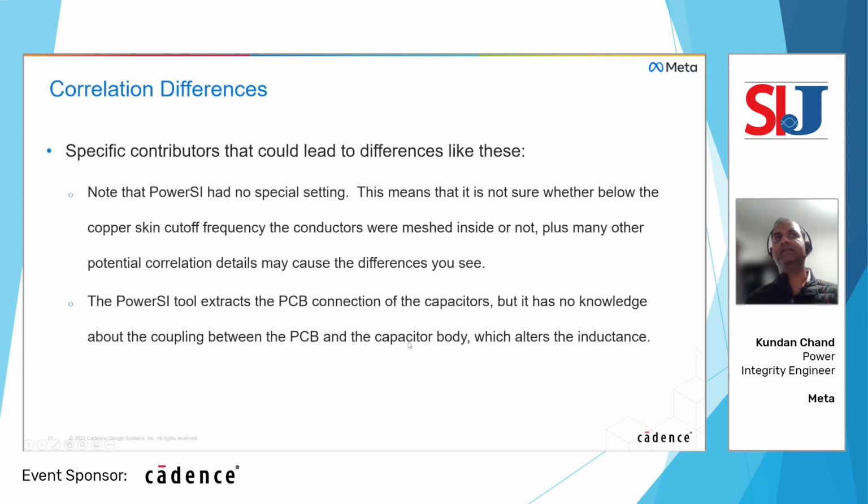One of the other things, it's not mentioned, but I want to point out is we did measure the individual capacitors in our lab, and found that compared to the vendor S2P models, the capacitance portion was well correlated, but the inductance or the ESL of these caps was not the same as the vendor S2P model suggested. So that could also be causing some differences in our correlation results.